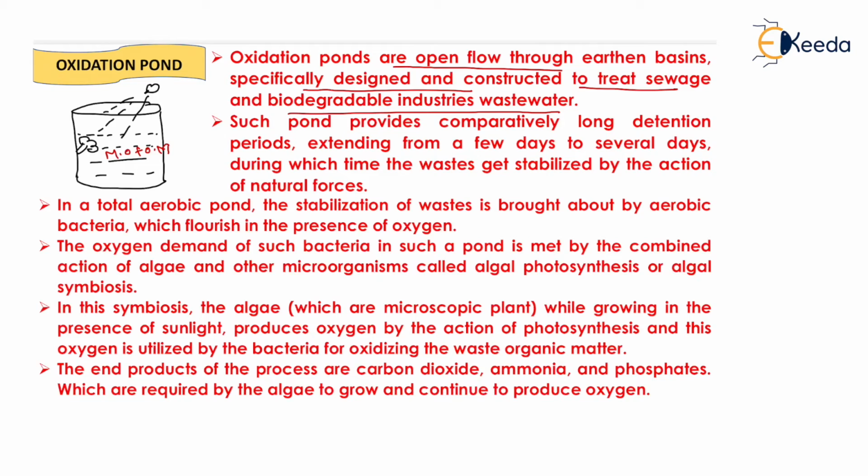With the help of this sunlight, the algae perform photosynthesis and release oxygen into the oxidation pond water. This oxygen is consumed by microorganisms, which decompose the organic matter.